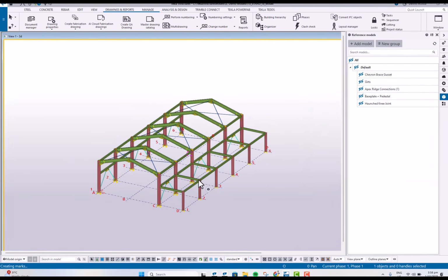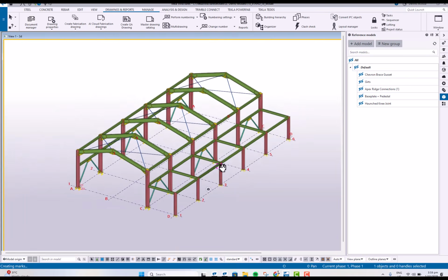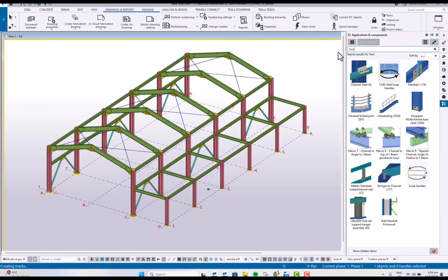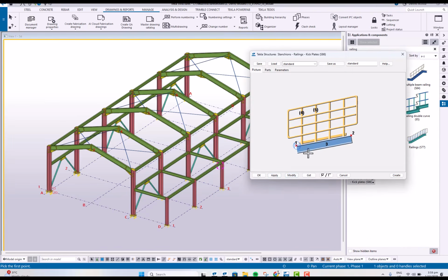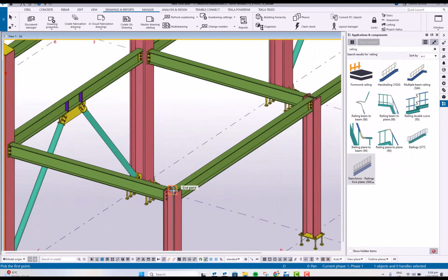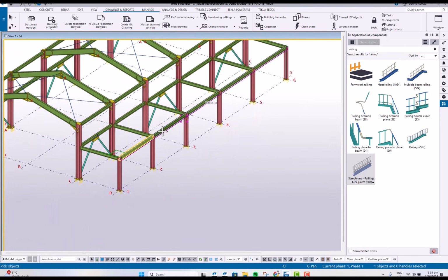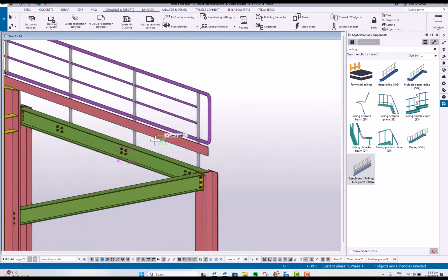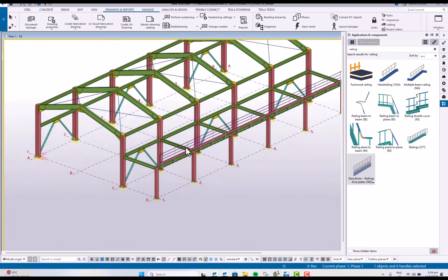Now, let's move on. Since I have a little bit of time, before I create the drawing, let me just show you another option. What if you want to add a railing? This one will not take a minute. So here I have the stanchion railing. Apply and okay. All you have to do is pick this point and this position. This one is just an additional 1, 2, 3, 4, 5, meaning all the stanchions will be created on that particular line. So here, as you can see, the railing is already created. If you have a miscellaneous item in this building, you can also add the railing.